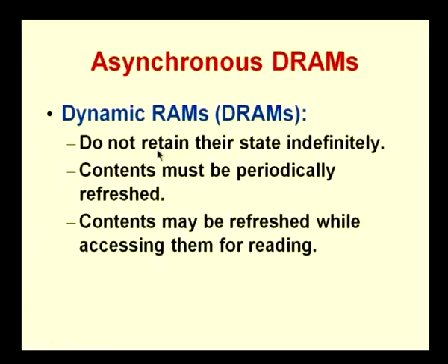Another type of RAM that we use is called a dynamic RAM. The moment we talk about a static something, dynamic will be something slightly different from that. So, let us look at what a dynamic RAM will be. The basic difference is that dynamic RAMs will not retain their state indefinitely. We said that a static RAM is a volatile memory, and once you switch off power, it will lose the data. But if you do not switch off power in a static RAM, whatever data you have written will be held in that flip flop forever as long as power is maintained.